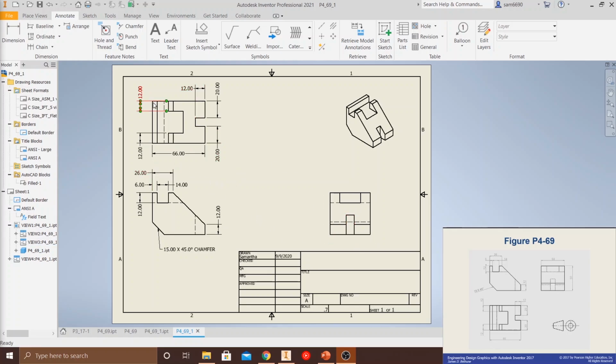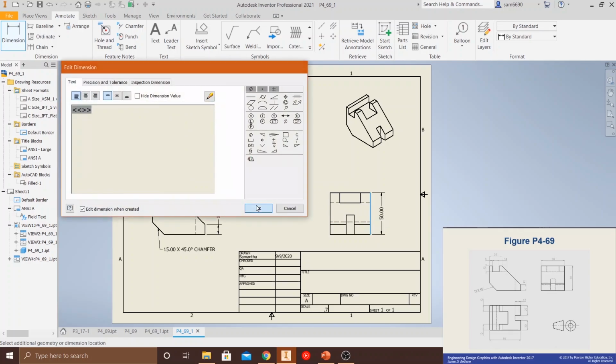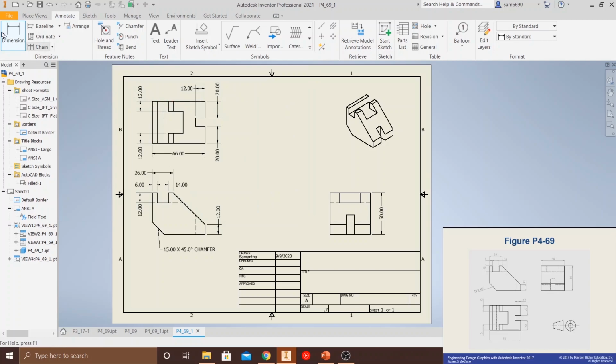We also already have this cut dimensioned, so we don't need to worry about that, because with all of the given dimensions that we have, they should be able to know this length, know how far in it goes, things like that. So what we're going to do is dimension the height and the width, because we don't have anywhere across in the area that tells us how tall it is or the width of it.